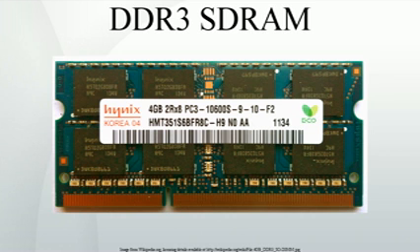Fractional frequencies are normally rounded down, but rounding up to 667 is common because of the exact number being 666 2/3 and rounding to the nearest whole number. Some manufacturers also round to a certain precision or round up instead. For example, PC3-10666 memory could be listed as PC3-10600 or PC3-10700. Note: all items listed above are specified by JEDEC as JESD 79-3D.